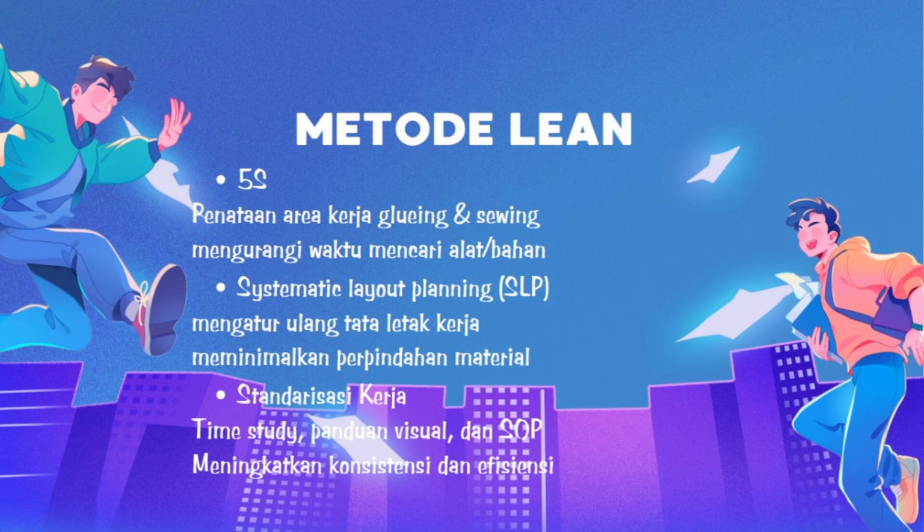The second method is systematic layout planning. This method focuses on analyzing the flow of materials between departments and designing a better layout. In this case, they redesigned the layout of the production area to reduce the walking distance and material movement between workstations. The third method is work standardization, where they used time studies to measure the time required for each task and created visual designs to ensure every operator follows the same steps consistently. This helped to reduce variation, improve quality, and make training easier.